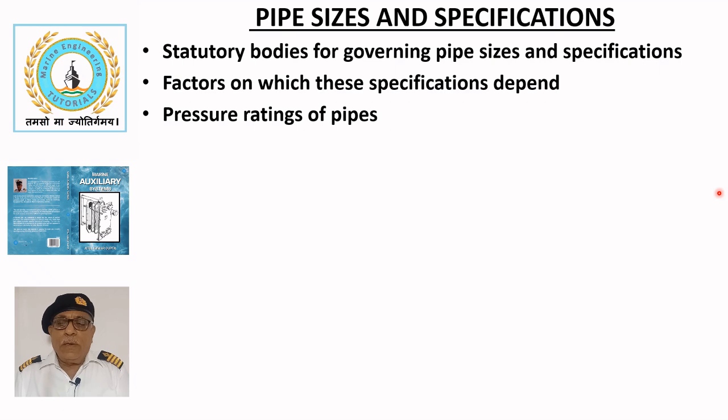High pressure piping are used for hydraulic systems, high pressure steam, fuel injection, etc., with a working pressure above 30 bar. These are typically fabricated from Schedule 160 pipes or other heavy duty specifications suitable for high pressure service.